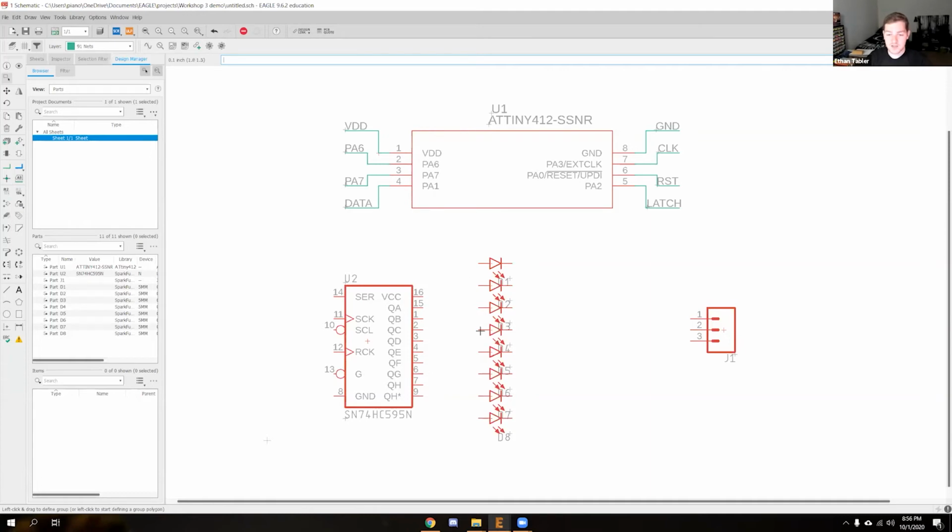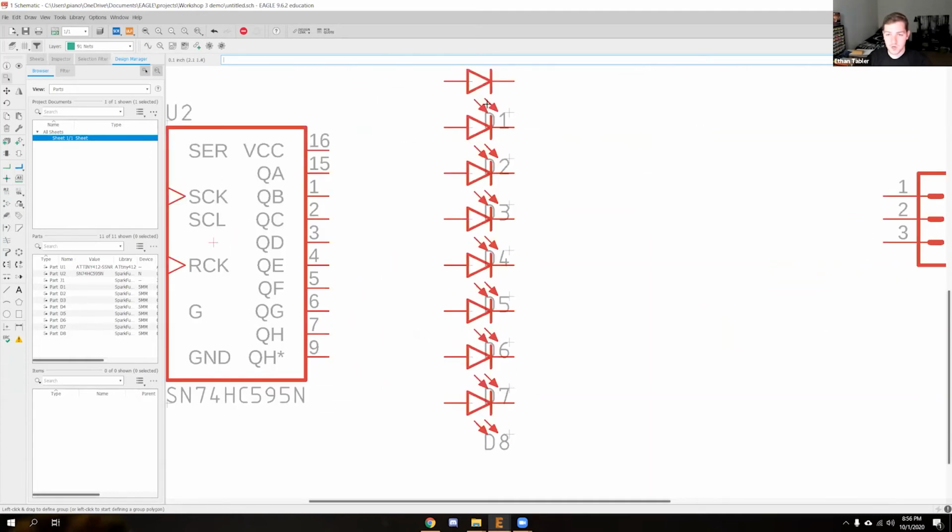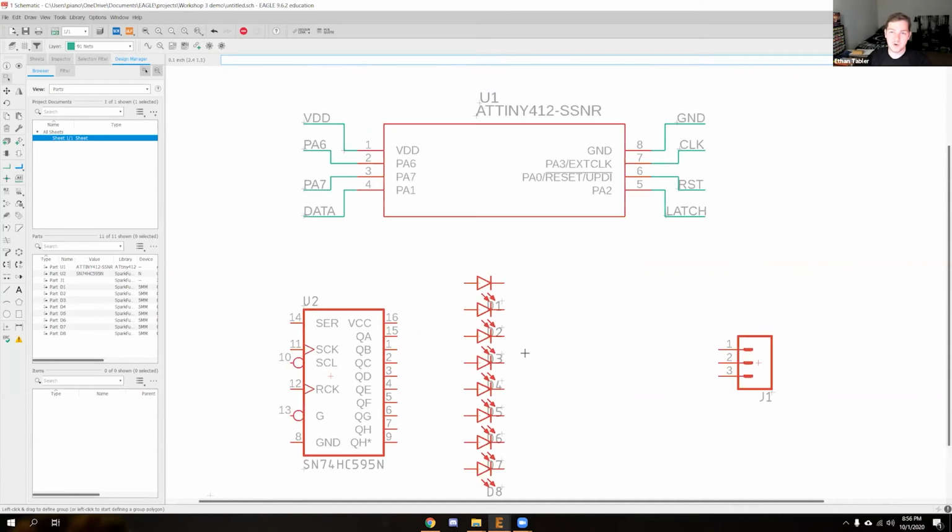So you'll see that all of these are also numbered. Each one of these parts has a number. So like this is U1, and this is U2. That's usually standard for logic chips. If you are familiar with the EE210 amplifier circuits that you build, you'll notice that it'll say like U1A, U1B, because a couple of those op-amp chips have 2 op-amps on one chip.